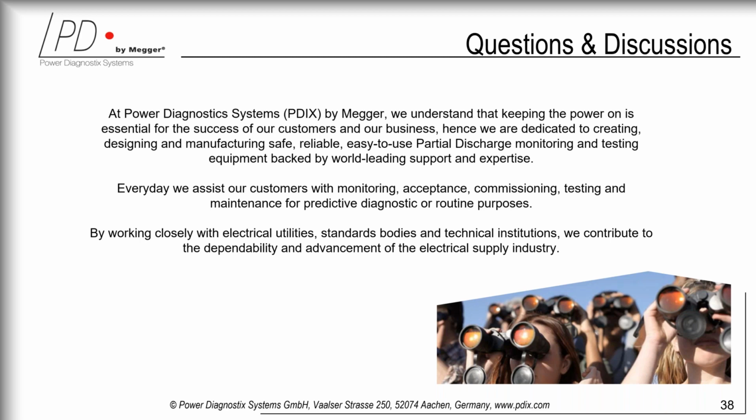Okay, gating. We have seen on one of the slides the disturbance antenna or a CT that we use to pick up external noises, noise pulse signals from ground sheets or from radiation, from corona, from overhead lines. And these pulses are brought to a separate input of the instrument. So it's a special analog circuit that is separating these pulses from the measurement pulse.